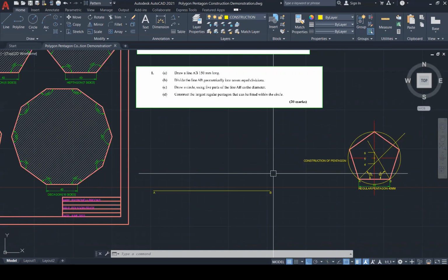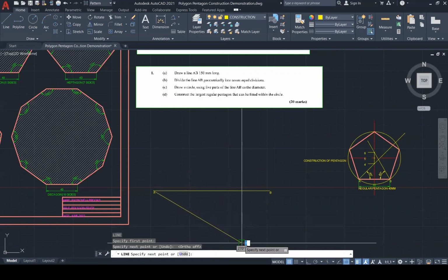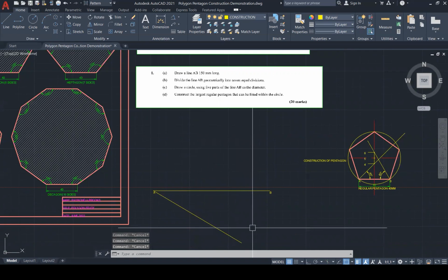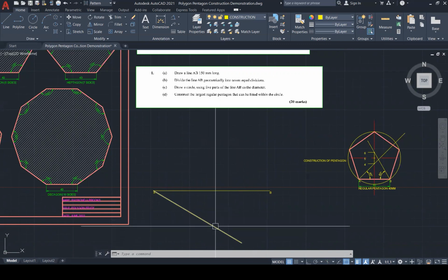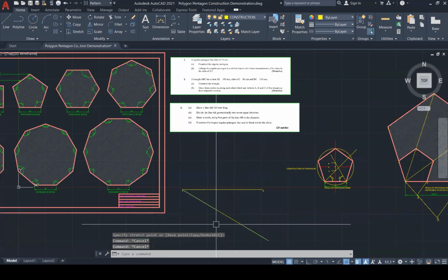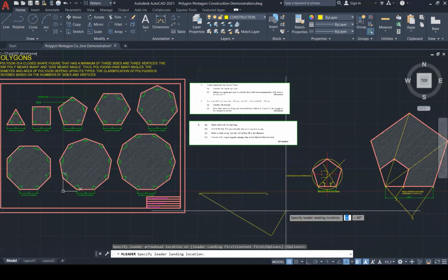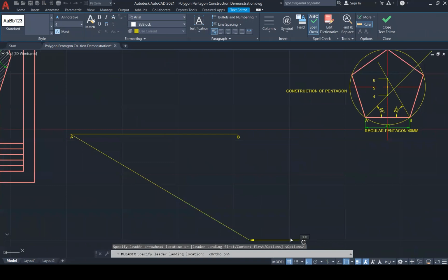Now the way to divide a line, I'm going to show you 2 ways. We can do it this way, which is the original way. So you just grab a line and you create your random distance. Whatever distance you want, that's up to you. So this distance could be here, or it could be all down here. I just pull it down to show people at home that this was a random distance. What is this line called? This line is called a construction line. So let me label this line so that people would know that this is a construction line. Construction line, any length.